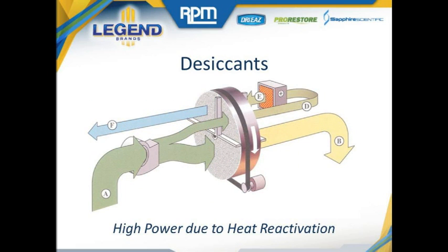In addition to the high power consumption of the desiccant dehumidifier, it's also important to remember that the silica gel or lithium chloride has a limited capacity to transport moisture. As the rotor in this image revolves approximately 1 time per minute, it has a limited ability to carry moisture into the reactivation phase. If water is evaporating at a greater rate than the rotor can carry and transport moisture, then humidity will continue to increase over time.